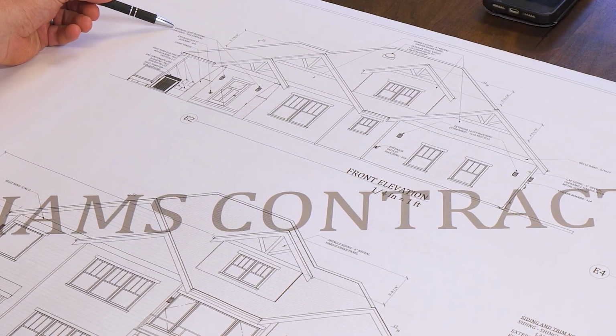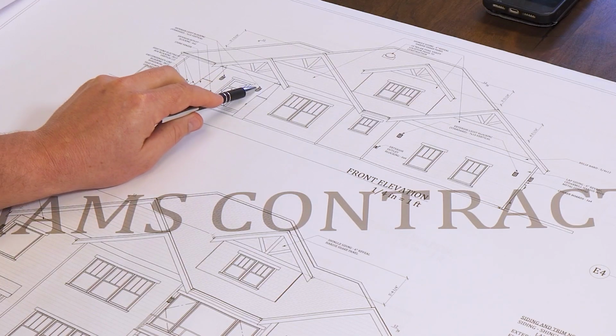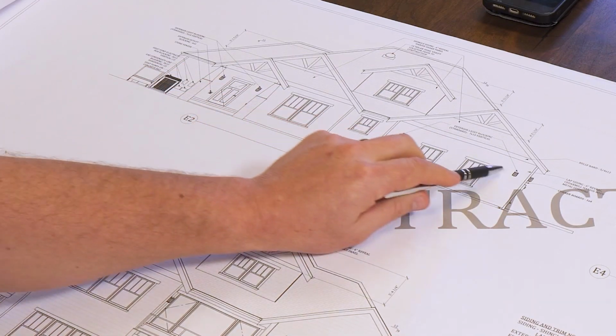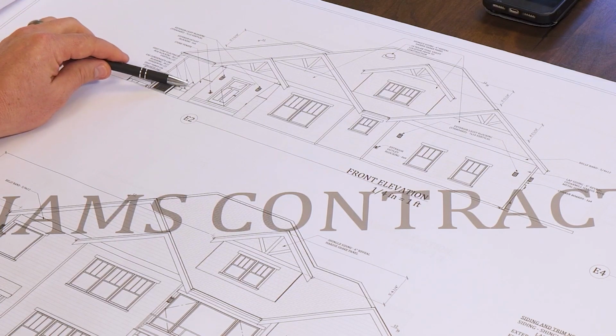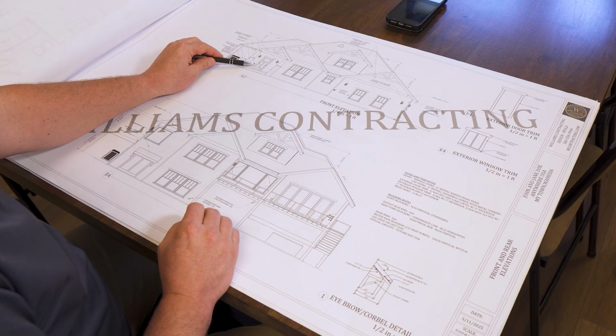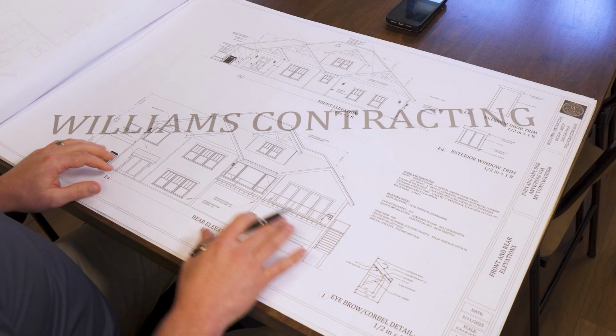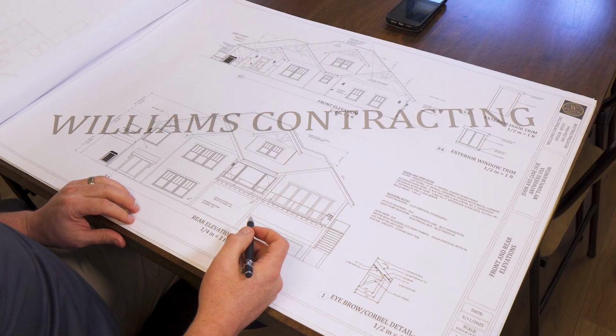Up here, we've got exterior lighting blocks, standard 7x10 vertical. So behind every exterior light, we're going to have those lighting blocks called out as a 7x10. We have a heat pump. We're calling out what these blocks are for the heat pump. We've got blocks for our outlets. Everything going on in this home, we like to call out what's going on in the exterior as a typical detail. If we have a special size or a special call out, that will be highlighted.